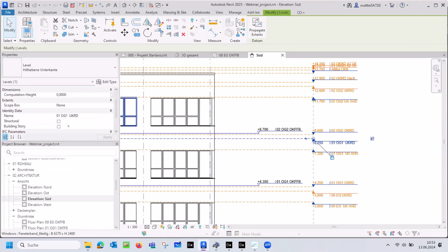It's just a layer, and this tick needs to be deleted. And if you would have this tick here also, then in DIALux Evo you would have also for the suspended ceiling one story, and that's then a problem that you have: sometimes a lot of stories in DIALux Evo. So if this file in Revit is, for example, not correctly defined, or the property is not correct.